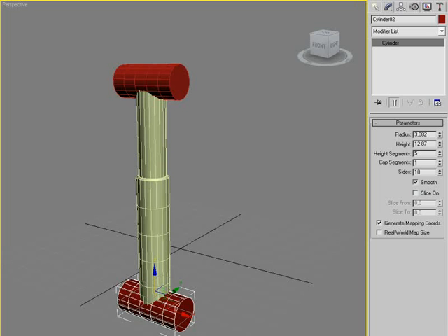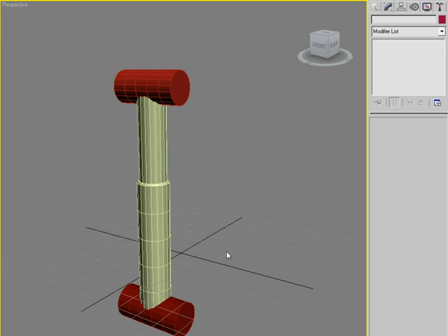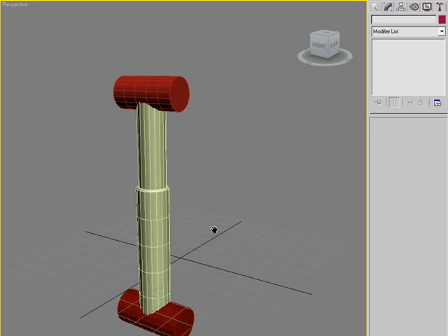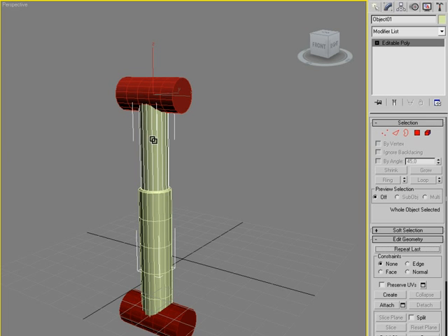And now we're gonna link these up the way they're supposed to be linked. Now it's important that we link this up in the right order, because if you add the constraints and then start linking, you might mess something up and get bad results. So let's link this up the way we want. Get the linking tool, and we link the upper part of the piston to this one.